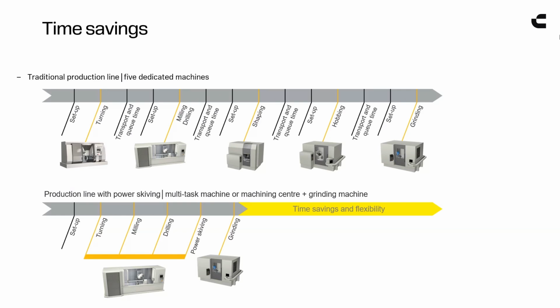Along with that, you can do things done in one, so they say. So with the addition of a sub spindle, you can do multiple setups automatically and be able to machine both sides of a component, relieve the stresses in it, transfer it back to the main spindle and back and forth until you're completed with that project.